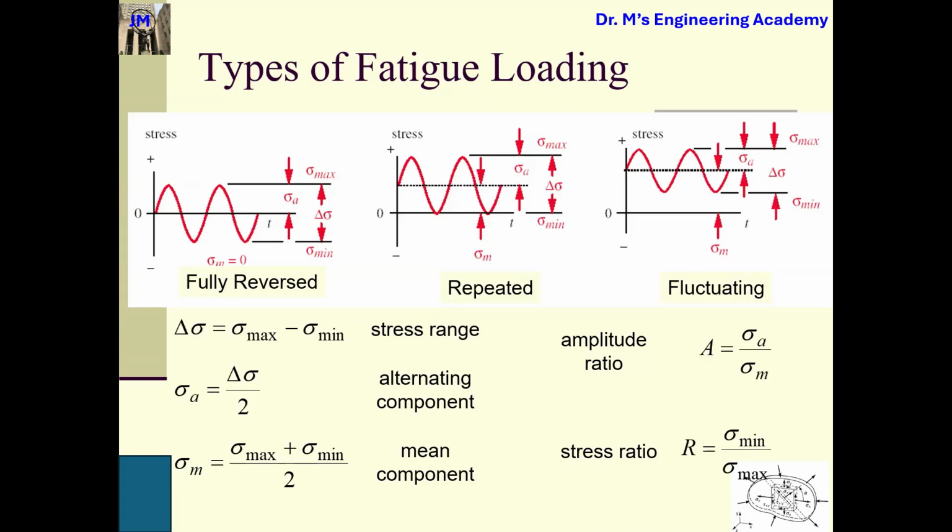Why? Because I have the stress, and even my lowest stress level is almost tensile. As I told you guys, tensile stress is bad. Because tensile stress is going to facilitate the propagation of cracks on the surface.